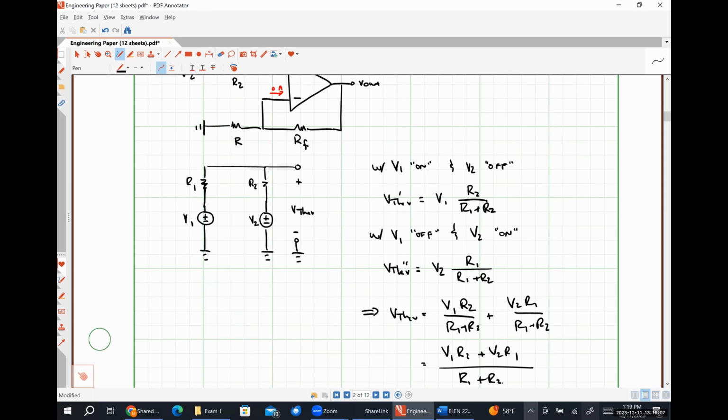So practically, we can do it, but from a figuring out how it's going to work standpoint, using the non-inverting amplifier, using the inverting amplifier as our basis of modification makes all of the math work out much, much easier. If we ever wanted to make sure that our output signal from our inverting summer was positive, or the same polarity as our input voltage, we would typically just add a second stage to convert that negative output voltage back into a positive output voltage.